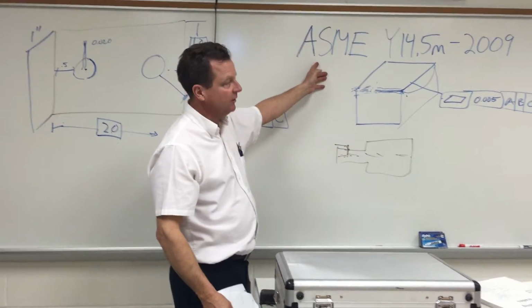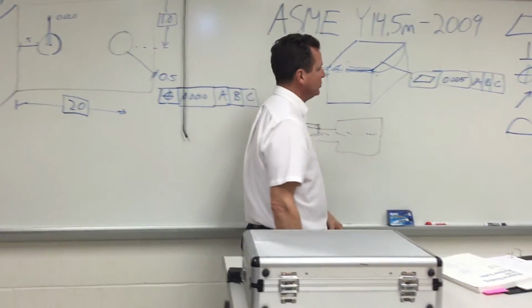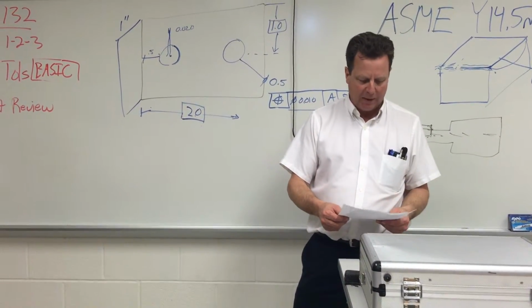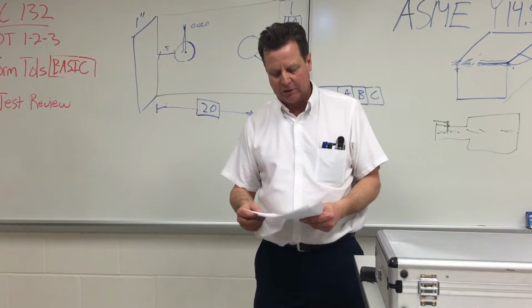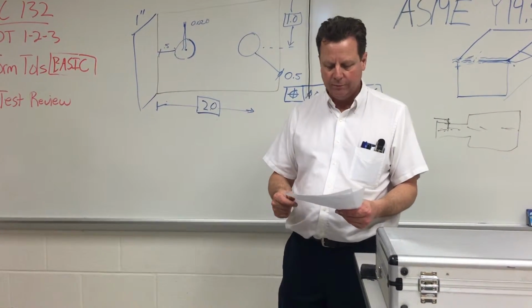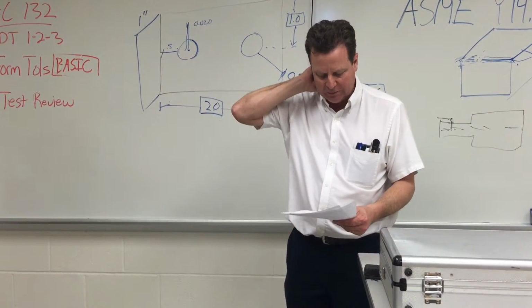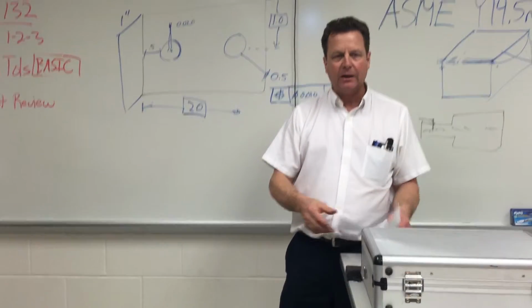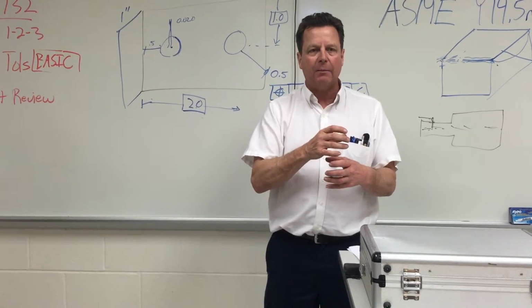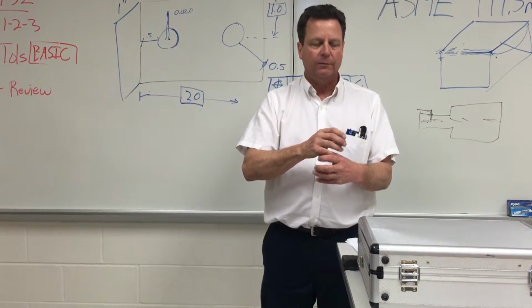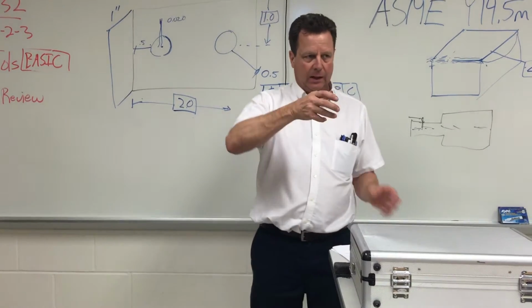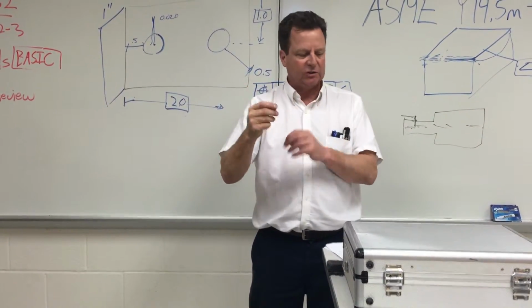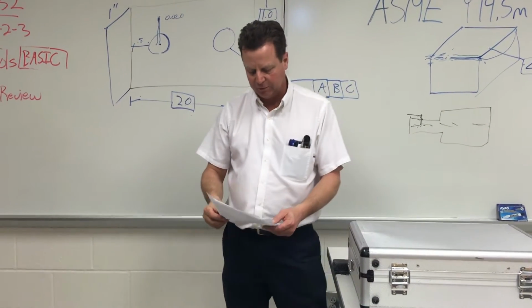This is the GD&T standard, and those are the 5 categories of the thing we talked about: maximum material condition, least material condition, and rule number 1. You should have all those things kind of memorized by now. We showed on the model that the datums of matching parts must be in common so that they will fit together, and if they aren't in common, then they may not go together because the datums and dimensions were drawn from different surfaces.